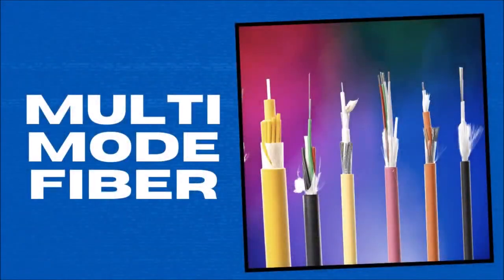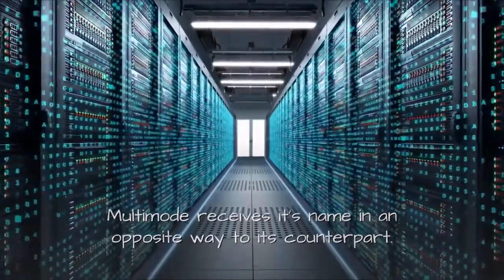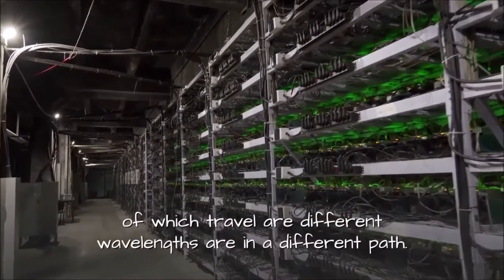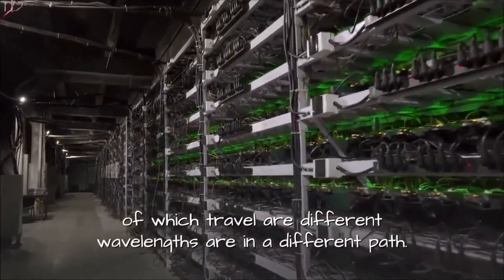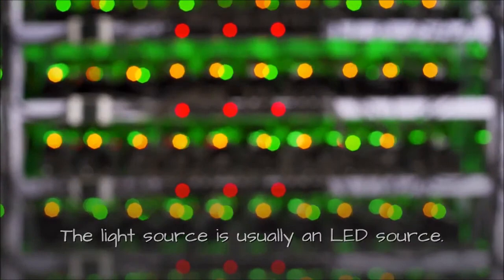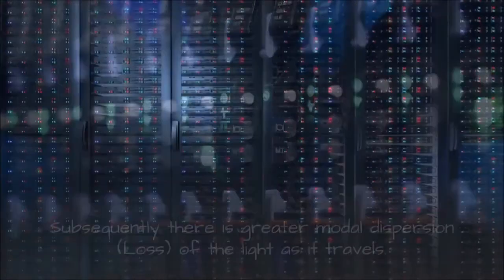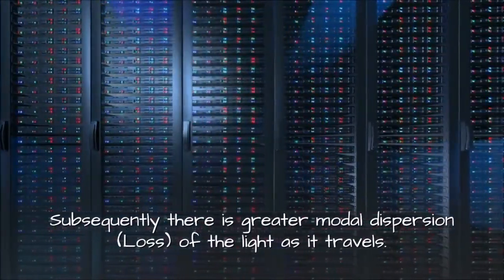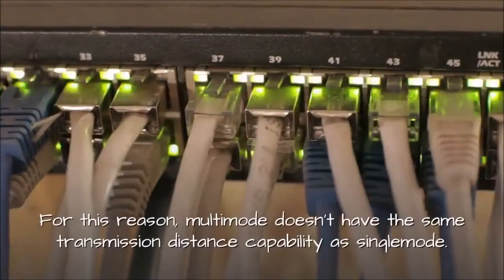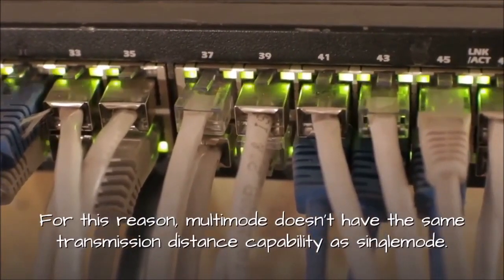Multi-mode fiber. Multi-mode receives its name in the opposite way to its counterpart. Multiple or many modes of light are transmitted down its core, all of which travel at different wavelengths or in a different path. The light source is usually an LED source. Thus the light is similar to shining a torch into the core. Subsequently, there is greater modal dispersion, or loss, of the light as it travels. For this reason, multi-mode doesn't have the same transmission distance capability as single mode.